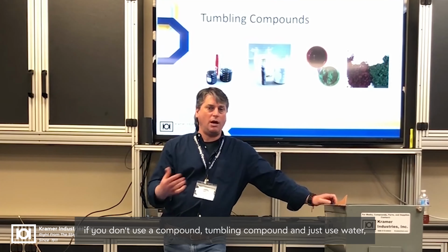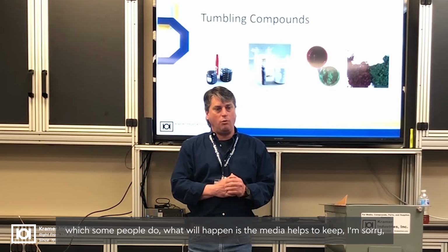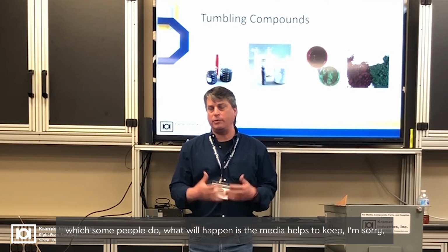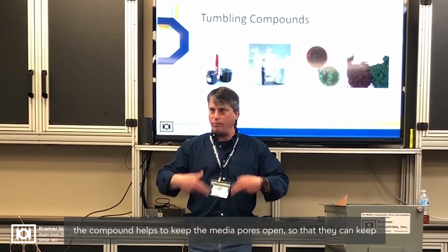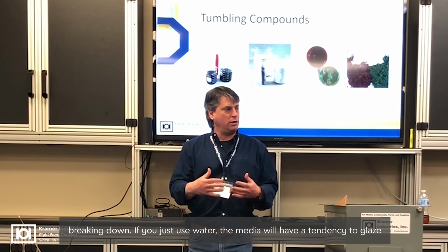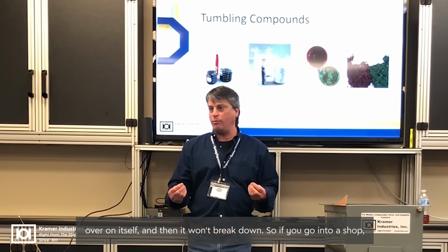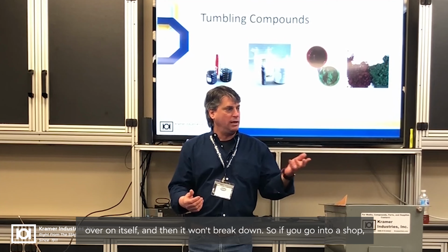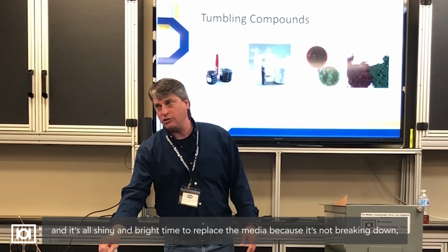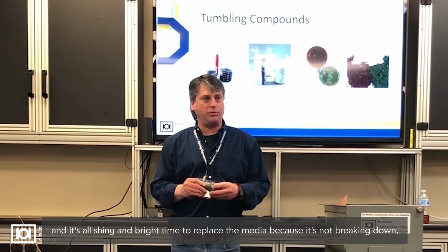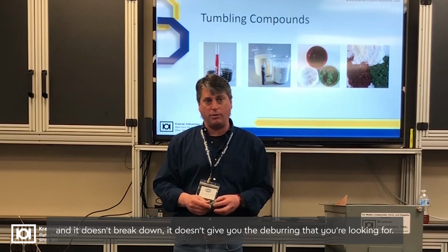If you don't use a tumbling compound, and just use water, which some people do, what will happen is the compound helps to keep the media pores open so that they can keep breaking down. If you just use water, the media will have a tendency to glaze over on itself and then it won't break down. So if you go into a shop and you look at the media and it's all shiny and bright, time to replace the media because it's not breaking down. And if it doesn't break down, it doesn't give you the deburring that you're looking for.